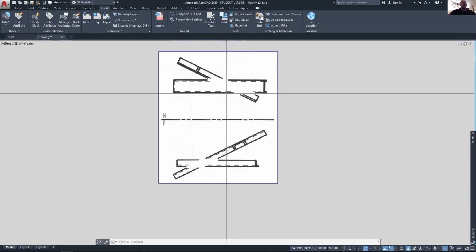But definitely I would draw the C channel or this horizontal beam in the horizontal plane as solid lines, and I would draw the L channel as it looks like underneath it. So those would be hidden lines. In the frontal plane, I would do the same thing. I would look at where it intersects and go to the horizontal plane to look at what is closer to the frontal plane. And it looks like the C channel is in front of the L channel at this point of intersection in the front view. So that is what the question's asking.